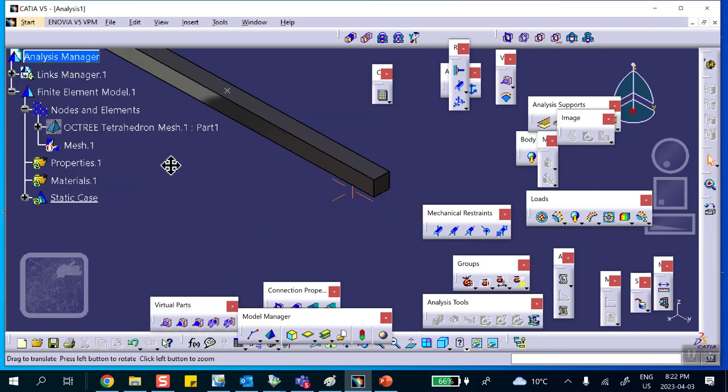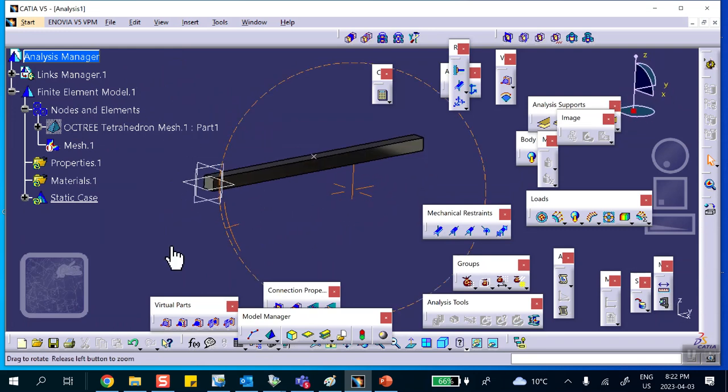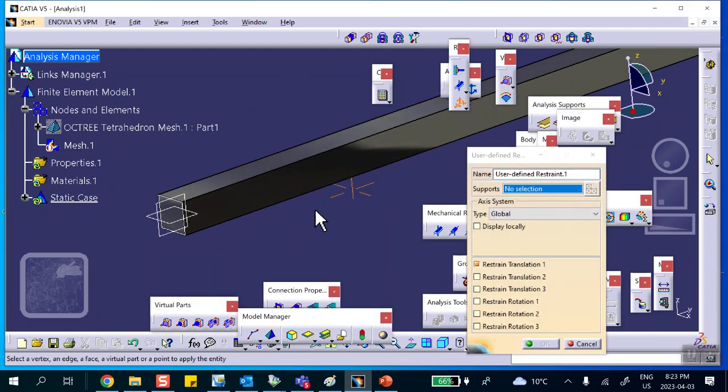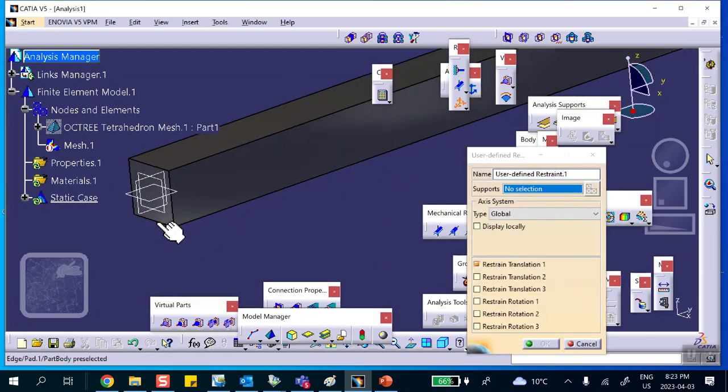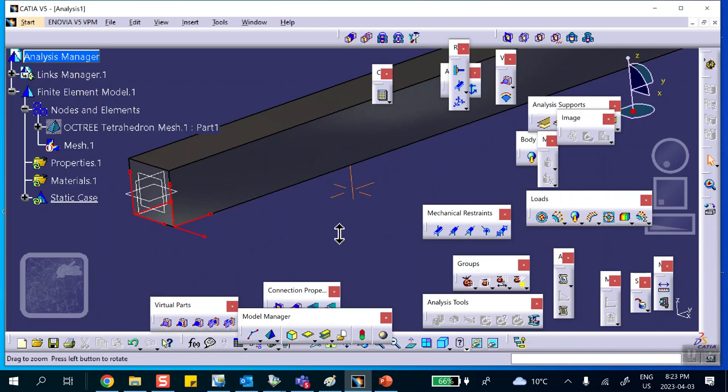Now, to make this thing simply supported at the two ends, we have already done things like this before. In one of the tutorials last week, I did, for example, a pivot here and a virtual part. But initially, I put this thing on a pin and do the same thing. So I'm not going to use a virtual part. I'm going to do that very straightforwardly: take this, say that it does not move in X, Y, Z direction. But aside from that, this is fine.